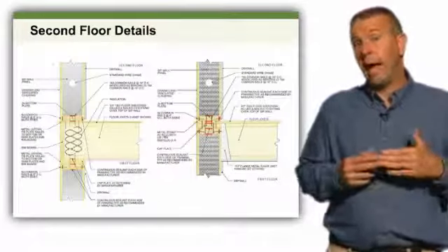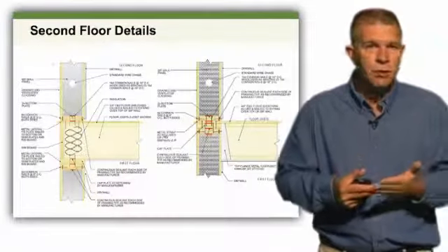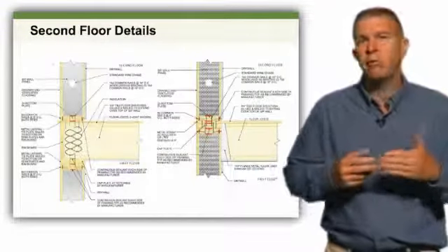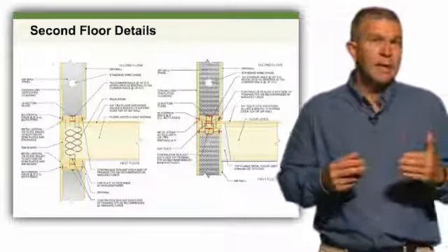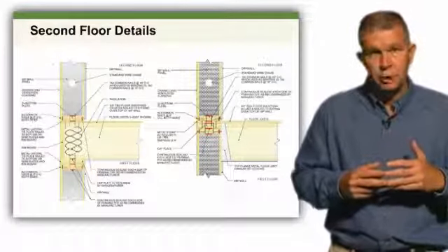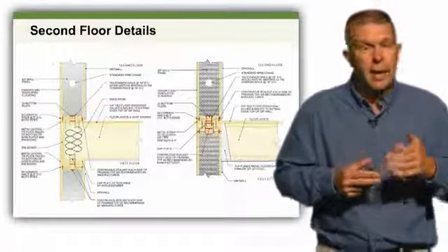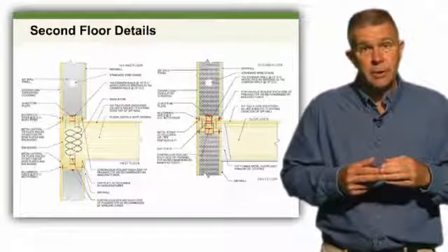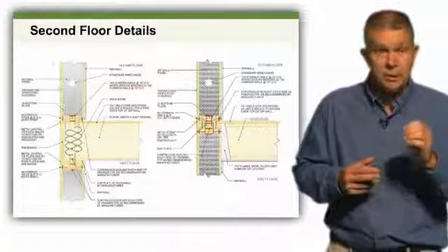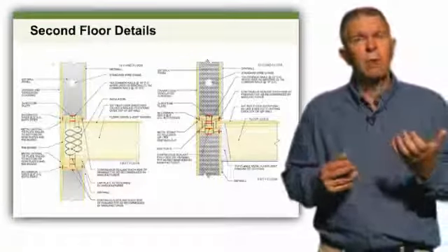As we move up the house even further towards the roof, we get to the intersection of a mid-level floor system. In this case, let's say we've got a 2-story house. We get to the top of our first floor walls, and we're going to put a floor system on. Well, in most cases, platform framing, as you see on the left, is the typical detail which most conventional framers use. The top of the wall, they platform frame the floor system, and then they start anew on top of that. However, you can do the same thing with SIPs in a platform configuration, and again, it's that floor system that may lead you to a lot of air leaks that you're not going to be happy with, or an obvious choice may be what you see on the right, which is what we refer to as the hanging floor system.